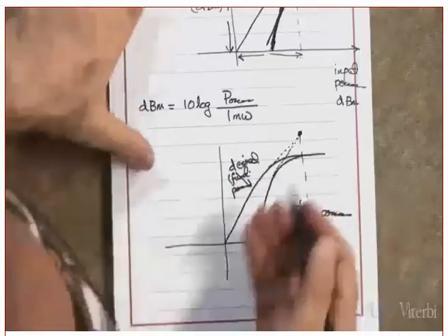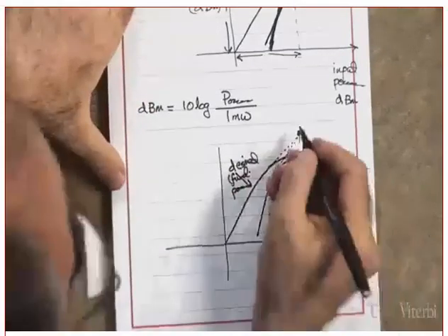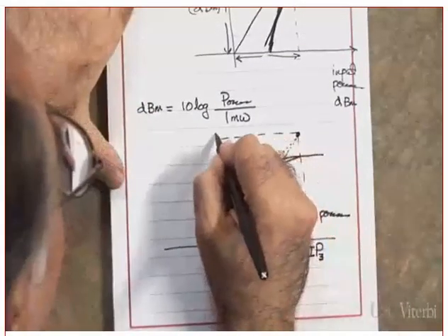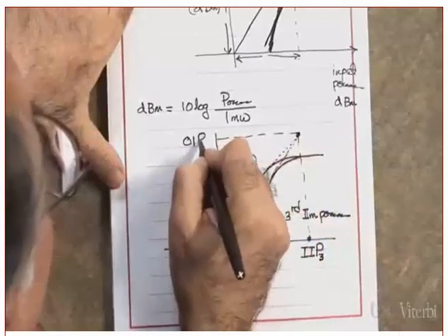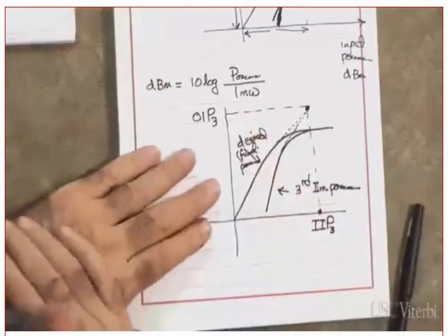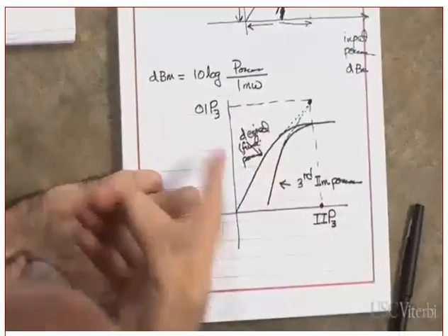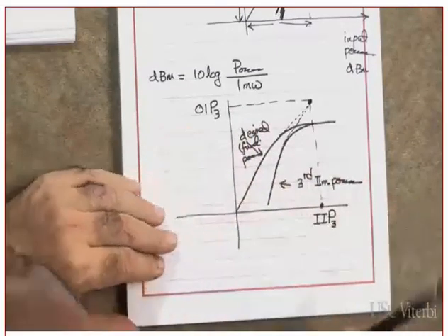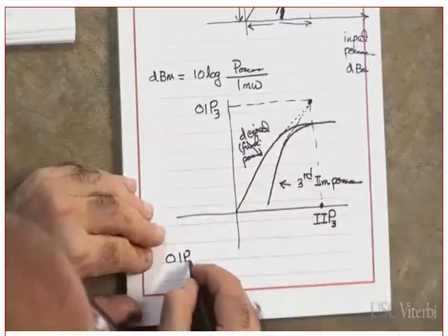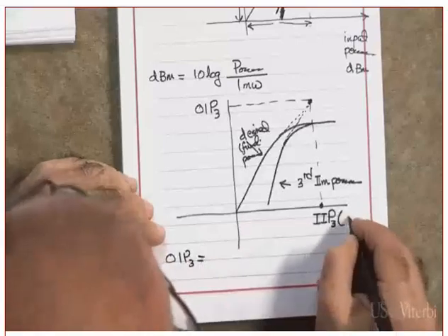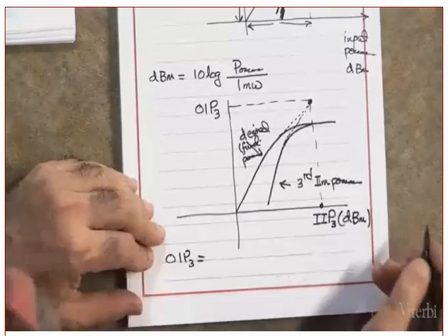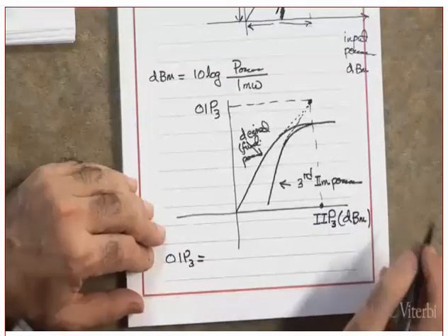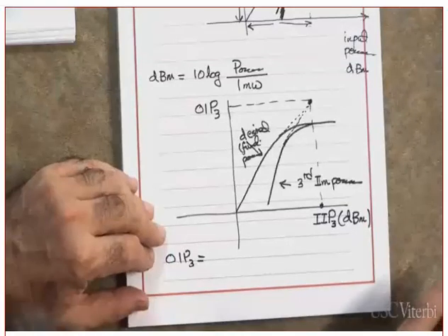I'm just getting, where is the OIP3? Ah, very good. This one. Did you get it? Question number one. Are they related? What is the relation? In other words, what is OIP3? Units. No. The intercept point is not in dB. In dBm, it's power. Clear?